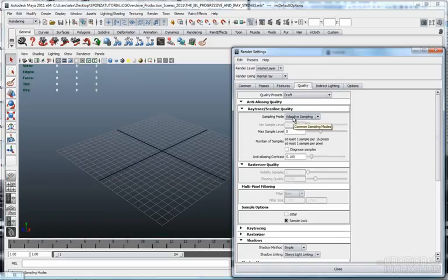And as I said before in the presentation, the adaptive sampling mode uses tiles, which means the image in the main render view is rendered in tiles that go parallel until the final solution, and you have no chance to see the image until all the tiles are rendered.